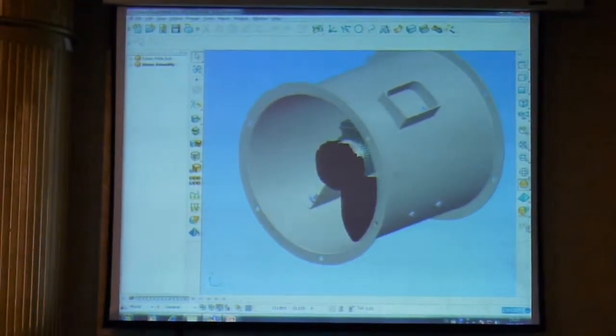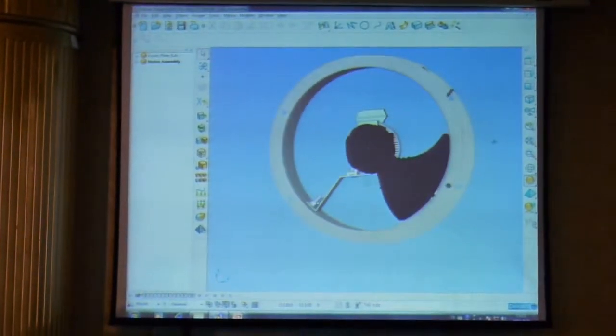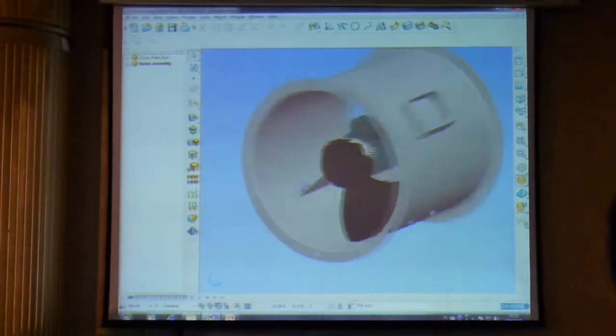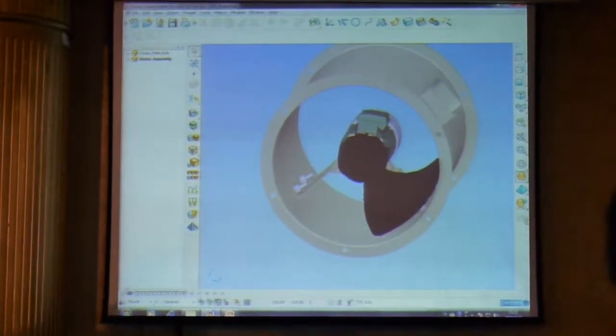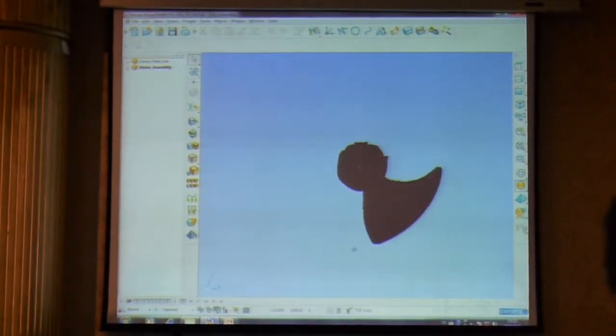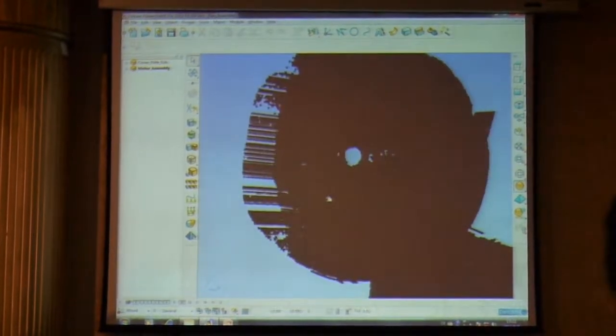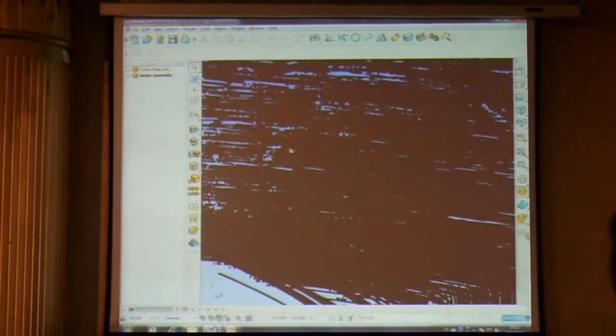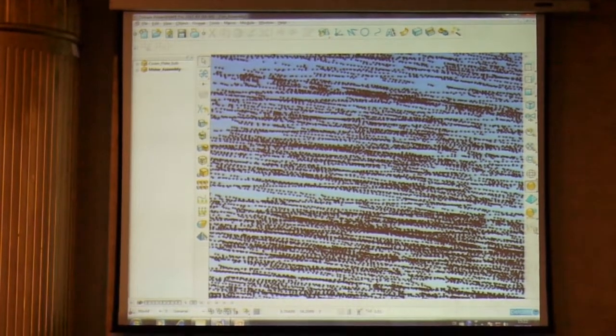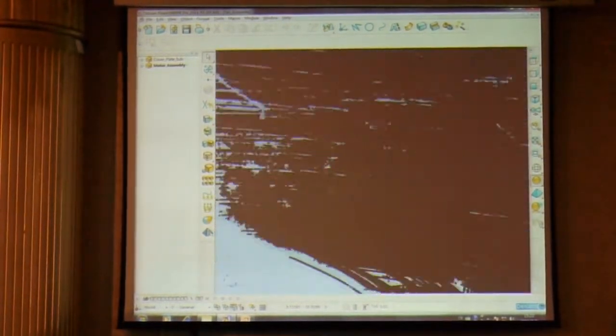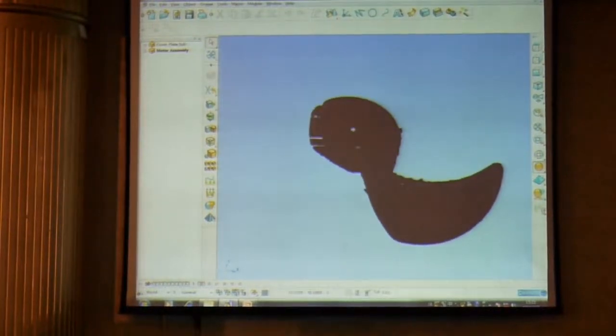So this is PowerShape, and you can see here I've got the basic design, the basic assembly in place. Let me just turn the assembly off and zoom in on the point cloud. Okay, so this is actually a cloud of points. And if I zoom in, you can just about make out the lines that the laser captured. And like I say, you tend to go over this type of data, the same area multiple times.